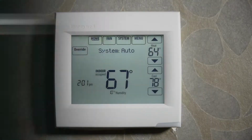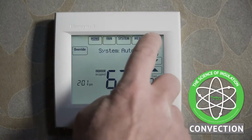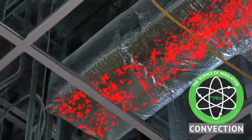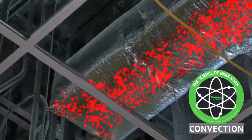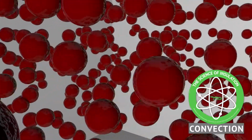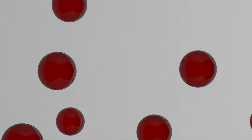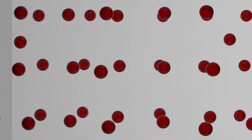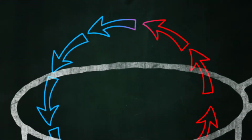Convection is on display when you look at the heating systems in some rooms. The heated air has molecules that are moving at a high rate. Heat is the result of molecules moving. The more heat in the air, the faster the particles are moving. When those particles bounce against each other, they create more space between them. The more space that is created, the less dense the air becomes. When the air is less dense, it rises.